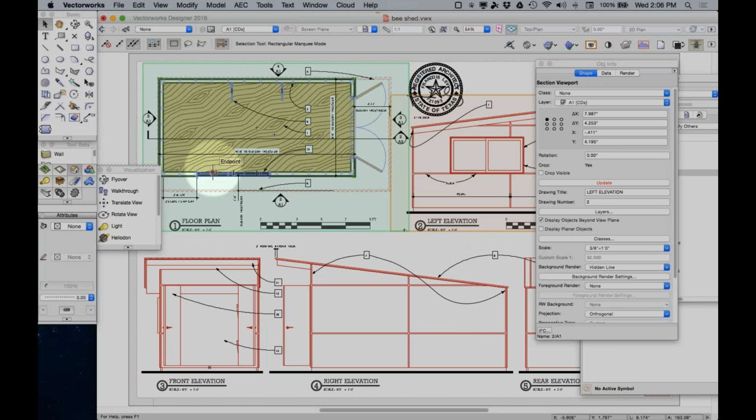Okay, one more question, and then I'm going to let you go. Can you get complex fascias in the roof and gutter components without modeling them separately? There is a fascia accessory that can be applied to the parametric roof object itself.